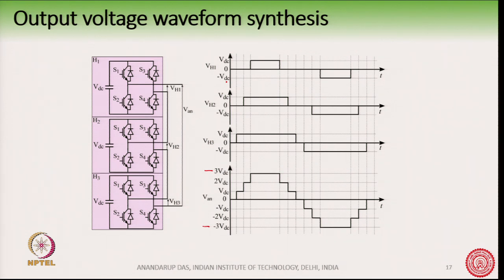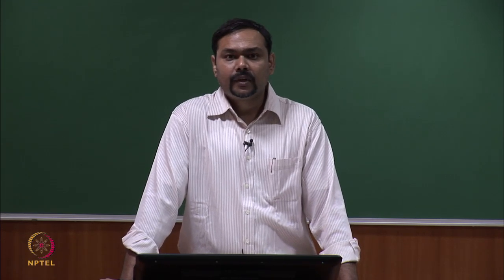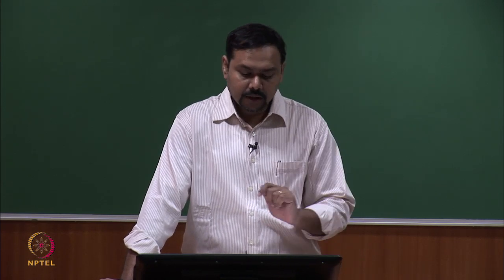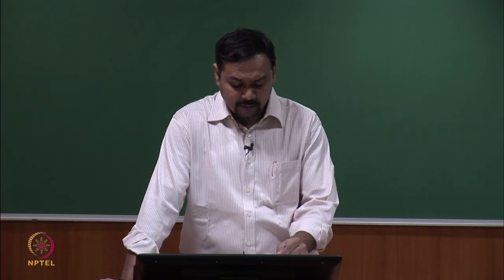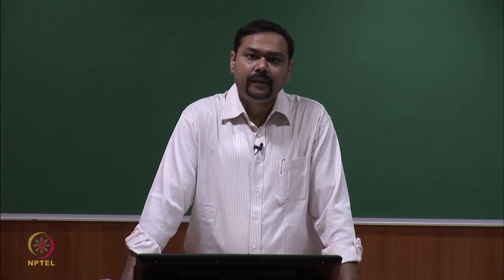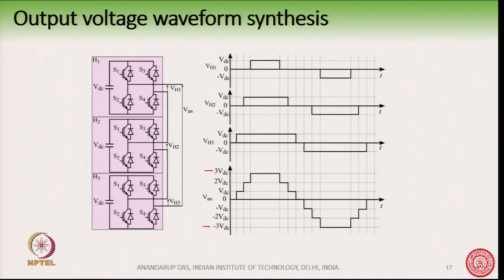Therefore, by using low voltage rated IGBTs in each cell, we are now able to produce a high voltage, because the IGBTs in each cell are rated for only VDC. This is the rating for each IGBT.